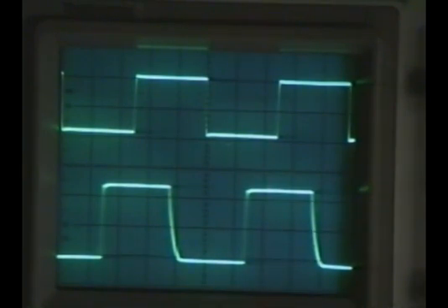If they weren't locked, by the way, it would just sort of be a mess. I'll show you what it looks like in a minute. Well, here, you want to see what it looks like unlocked? There you go. There it is unlocked. Okay? And what's happening is the oscilloscope is syncing or locking to the input waveform, and you can see the output one is doing weird stuff there. Okay, so that's not locked. There it is locked again.